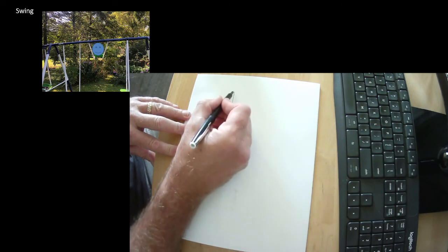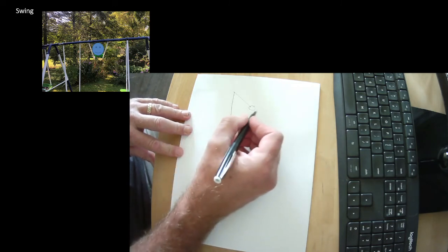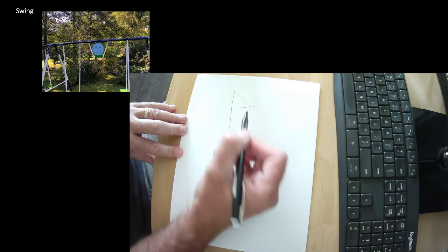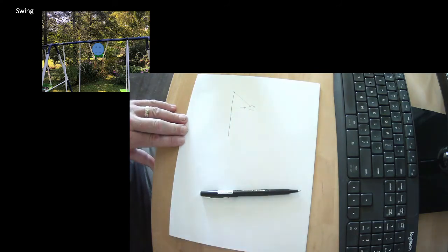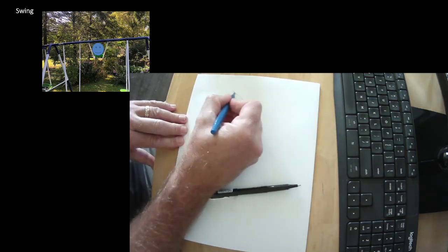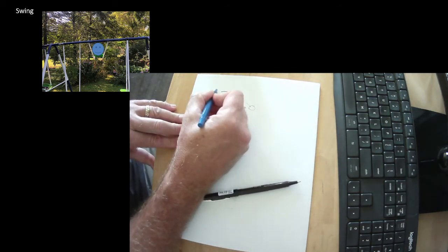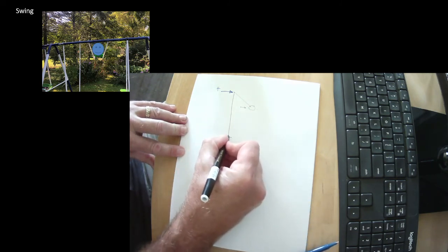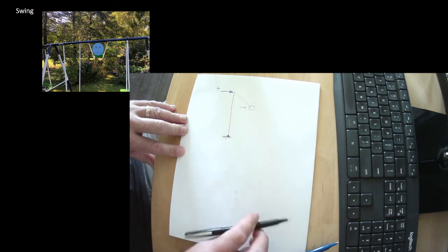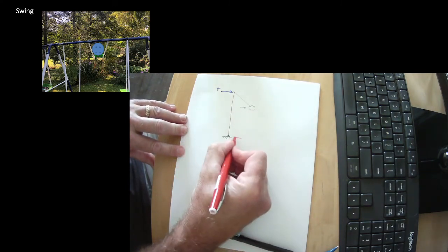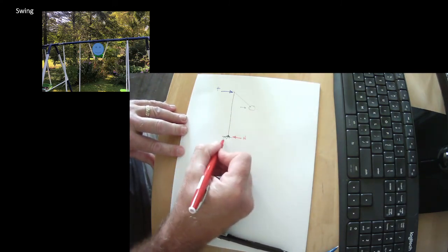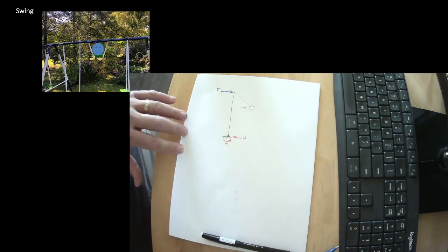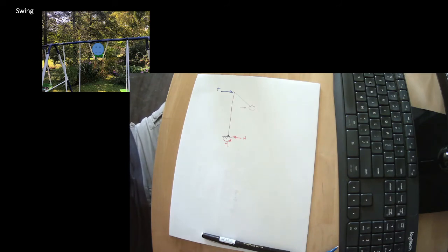We have a pole, we have a ball, somebody has pushed this ball, or is pushing this ball, so that even though this is a dynamic thing, we're going to represent that force with a static horizontal force. Fixed at the base. What holds it in place? We have a horizontal reaction, resistance, and a moment. So it's a simple cantilever problem.